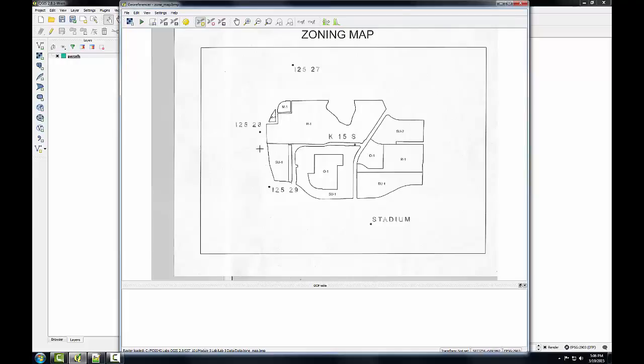So in other words, when I enter a control point, I'll be clicking on one of these points, and QGIS will read the coordinates. So that mouse click will be the source coordinates. The target coordinates are those that we're going to georeference this into, the State Plane, New Mexico Central. Those target coordinates are going to come from an NGS website that is detailed in the lab document. So the next step is to enter control points in the georeferencer with the Add Point button. This is the Add Point button here. It's enabled by default. So I'll click on I-2527.